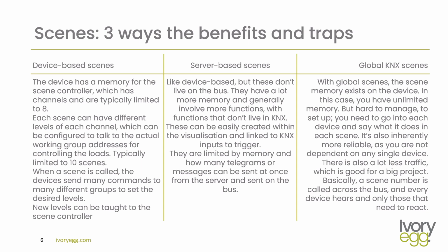Okay, the second way we're going to look at is server-based scenes. So these are quite popular too. Unlike device-based scenes, these don't live on the bus. They have a lot more memory and they generally involve more functions, including functions that don't always live in KNX, so it can be quite attractive. These can be easily created with the visualization and linked to KNX inputs to trigger them. So you can build a scene within a visualization, link it to a button, and then trigger that scene.